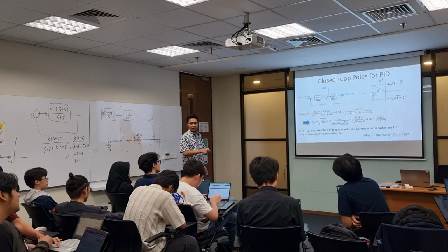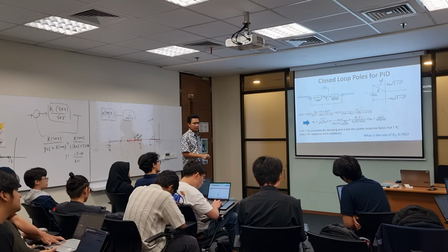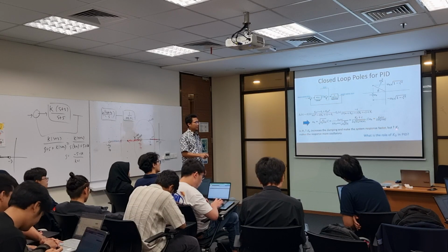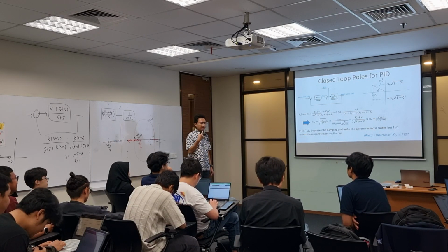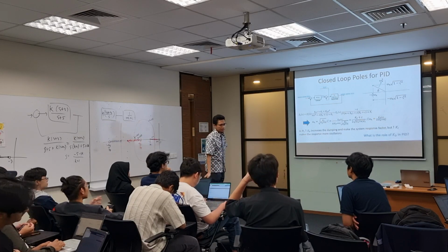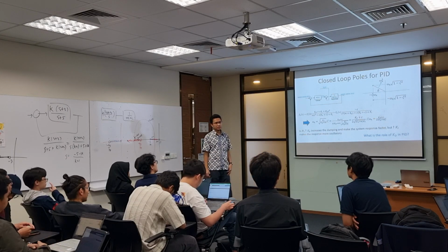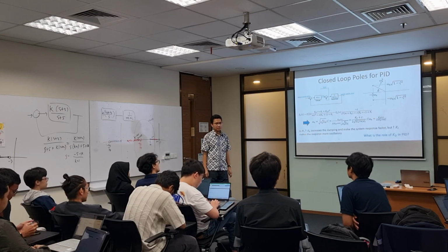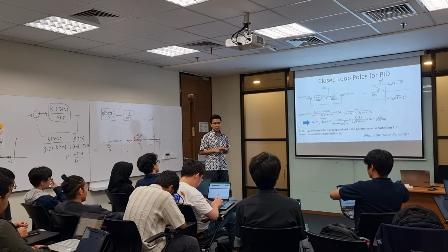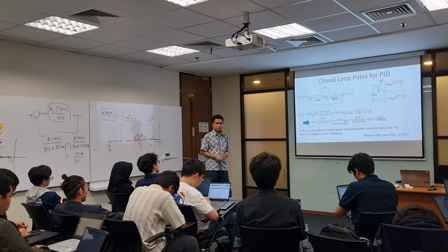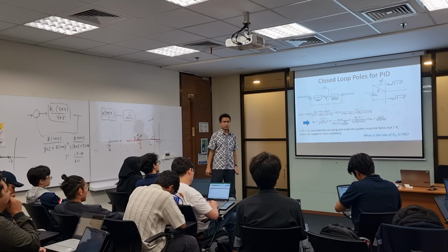From the PI controller, we know that Kp increases damping and responds faster, Ki makes the response more oscillatory. However, PI can reject disturbance. PID can also reject disturbance. You saw just now that PI can reject disturbance and make steady state error zero, right? So now what's the role of the derivative controller in there?